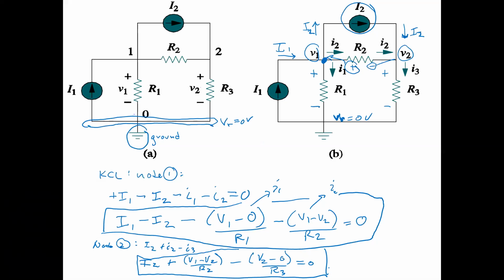So from that framework, it's pretty cool, right? Once you know those node voltages, you can figure everything else out, so you basically solve the whole circuit just by doing those two equations. It's a really systematic way, and if you have more nodes in the circuit, you can easily expand this. You can have a 4x4 matrix to just plug into FreeMat. You could have a 10x10 if the circuit gets really complicated. You can basically solve any circuit using nodal analysis. It's a really powerful technique.